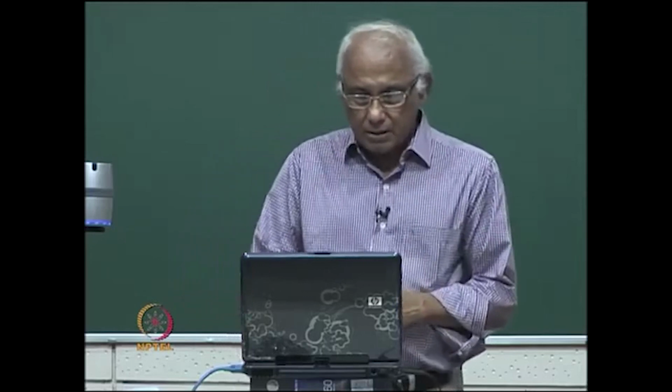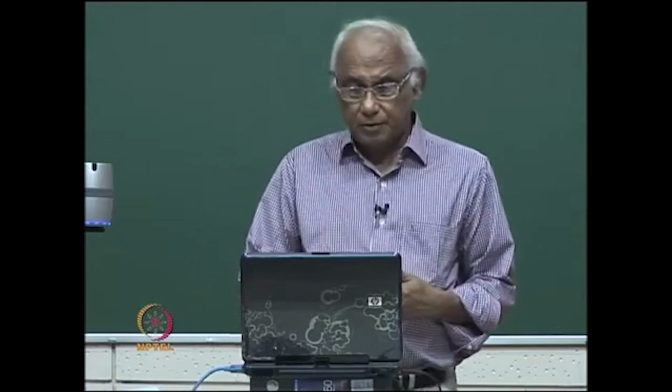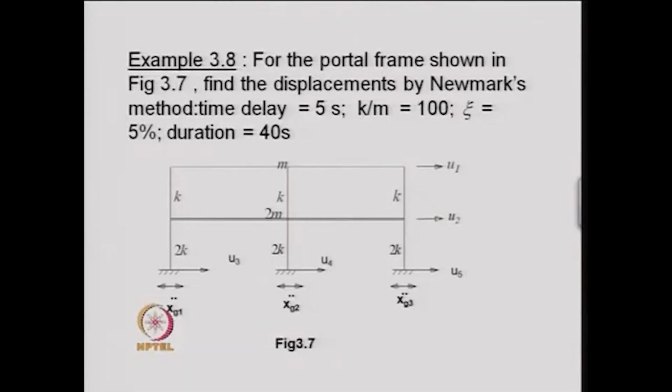In that, we discussed obtaining the frequency contents of the ground motion, and with the help of that frequency content of the ground motion, we solved the problem in frequency domain, obtained the frequency contents of the response, and then took the inverse Fourier transform to obtain the time history analysis.